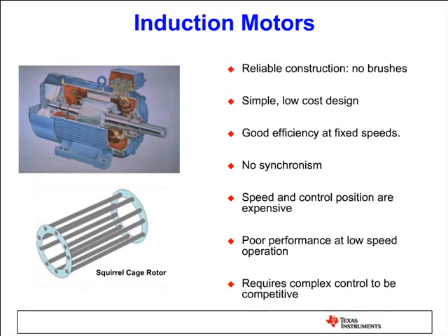And when we excite the power the stator, the rotating field indirectly creates flux on the rotor, on the cage bars. So that's how we create an indirect electromagnet on the induction rotor, and that induced field vector follows the stator field vector. The basic difference between induction motor and the other PM type of motors is, induction motor is not synchronous, which is okay. When your stator field spins at like 1500 RPM, the rotor will be spinning like around 1400 RPM, depending on the load.